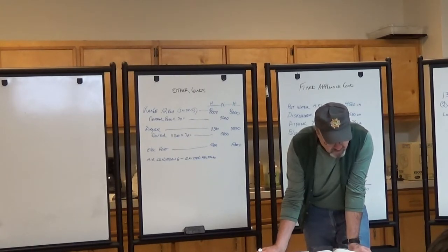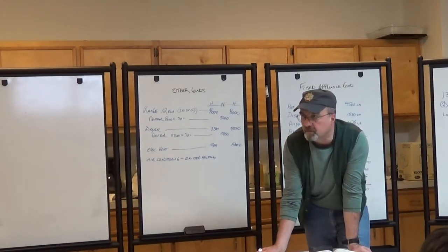So if we look at number 1, 125% of the full load current rating of the highest rated motor, the highest rated motor is what?